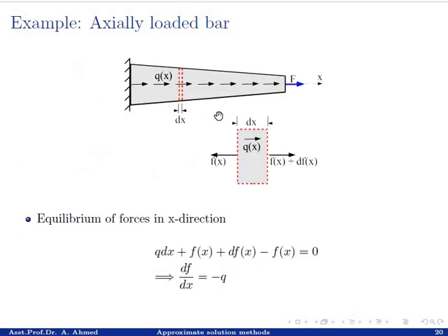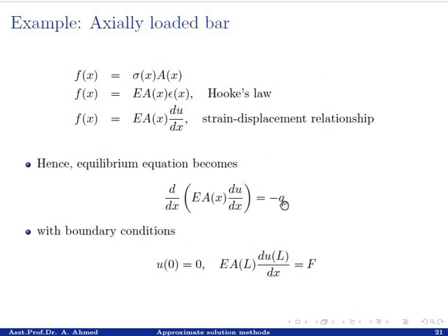Similarly, if you have some nonlinear material behavior, that can also be represented with the behavior of this one single differential element equation. So you can see that this is the advantage of the continuous formulation: you don't have the exact stiffnesses and exact equilibrium equations, but you have differential equations which can take into account complex geometries and complex and nonlinear material behavior as well. This equilibrium equation must be supplemented with some other differential equations, which are the boundary conditions.